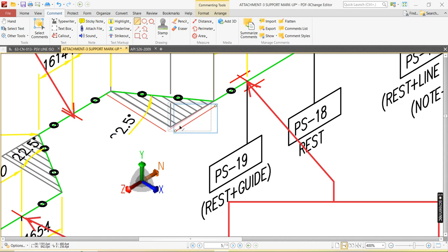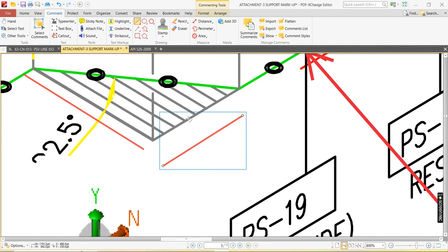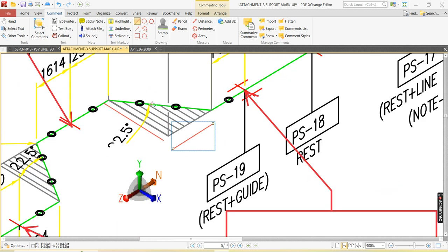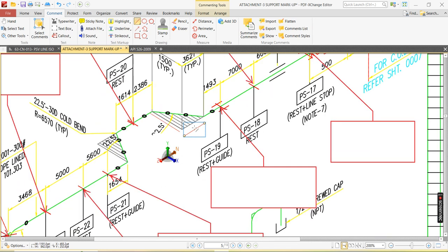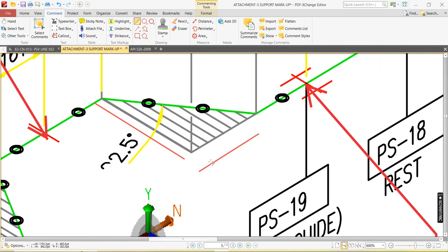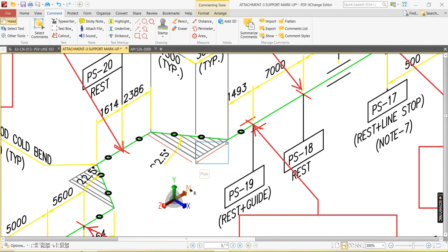Skew you have to understand properly, then only you will get a correct result. Okay. So this horizontal skew, this is horizontal. If it is vertical skew means the hatch should have been in the vertical. Okay, this you have to see properly, the hatch. So it is in horizontal direction. So line should have traveled in Z as well as in minus X.